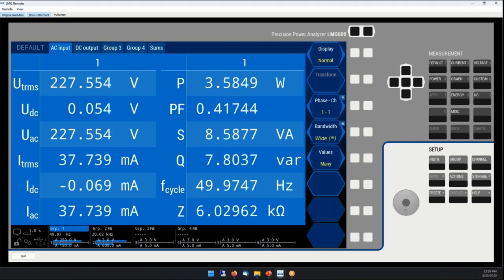The good thing is that the power analyzer can adjust this delay. So there are settings on the power analyzer for the range and for the expected delay. So you can correct that if you know more or less what the time delay from your current clamp is.